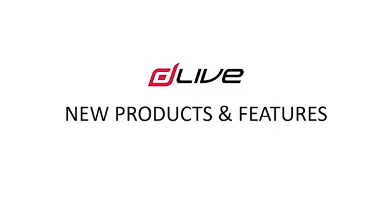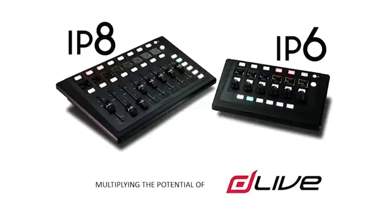I'd like to introduce you to a couple of additions to the DLive series, which expand the ecosystem and the flexibility of the system even further into installation. The IP6 and IP8, they are remote controllers for DLive. They're fully networkable, which means that you can run them on a standard Ethernet or TCP/IP network alongside any other TCP/IP traffic. They're also PoE compliant, so they give you the convenience of a single Cat5 cable to distribute control and power to the devices. And you can run up to 16 of each in a single DLive system.